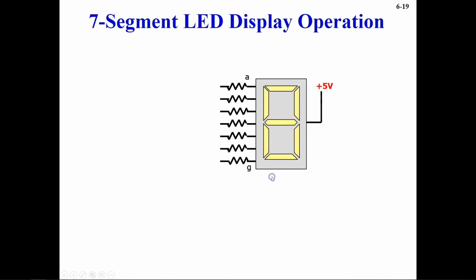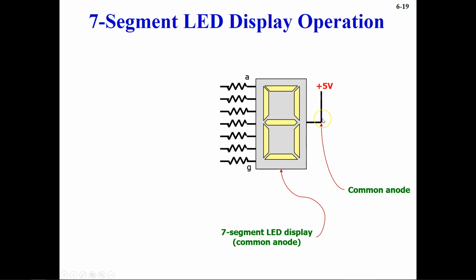And then you have an anode here, which is at this side connected to the 5 volts supply, and then cathode is here, from A through G is your cathode terminal. And then we have these resistors also. These resistors are the limiting resistors. So since this is your cathode terminal, let's see what will be the output on the 7-segment display if we have some input.